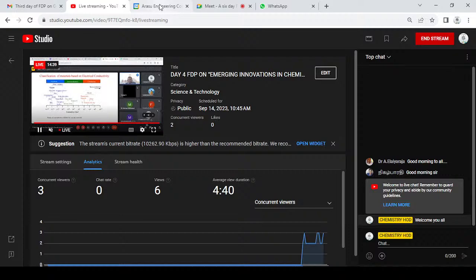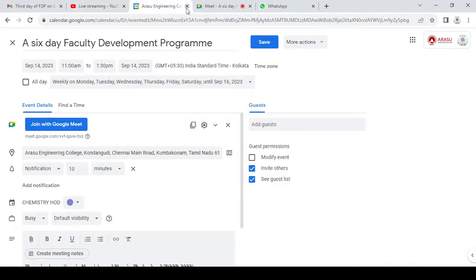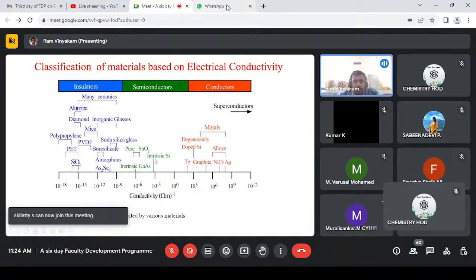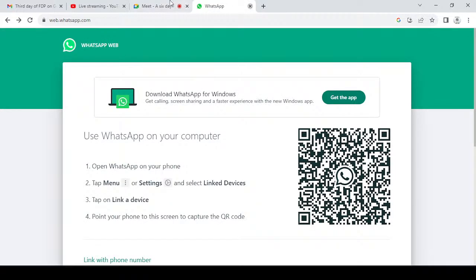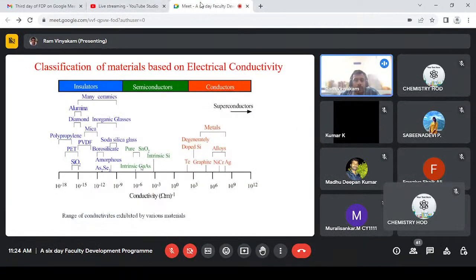So they have a conductivity of nearly 10 power 3 Siemens per meter. And others we have seen: elemental semiconductors will normally have conductivity on the order of 10 power -3, whereas compounds like gallium arsenide will have on the order of 10 power -6 Siemens per meter.